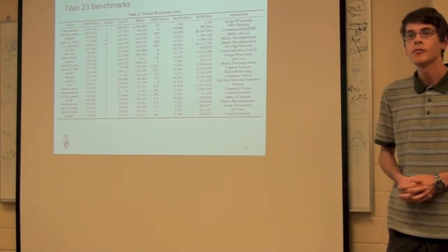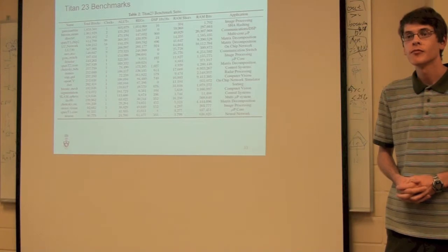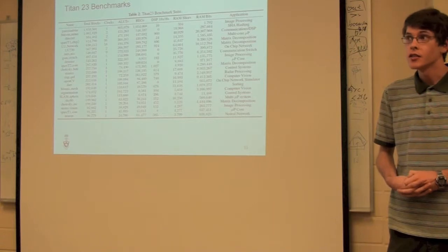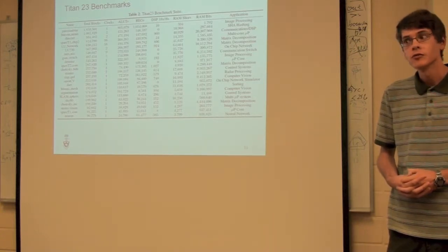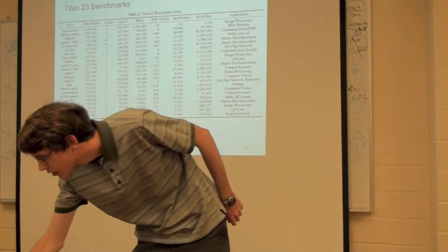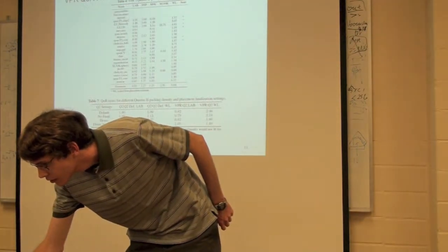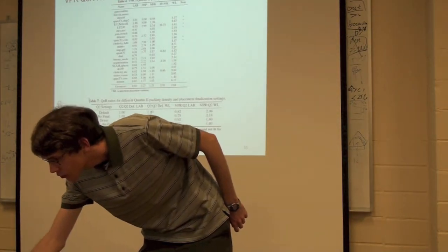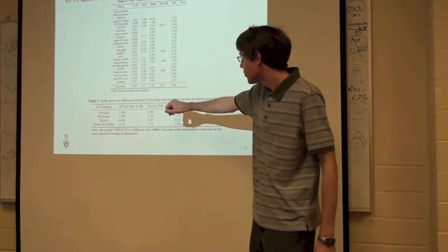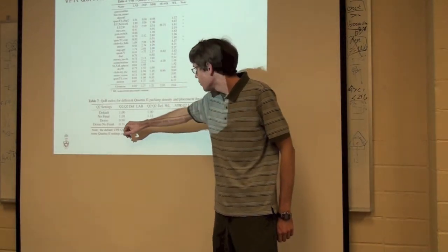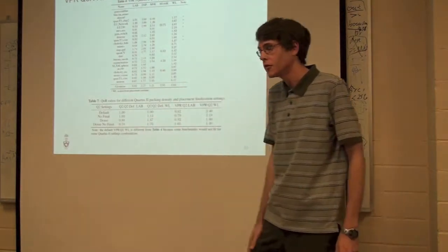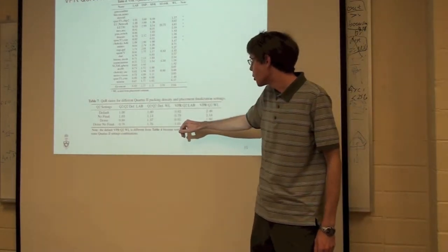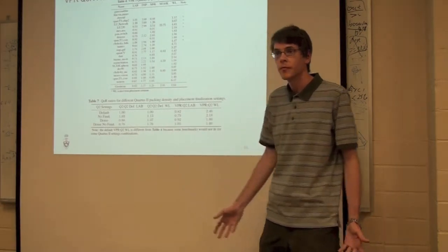Yep. About that argument, didn't you also mention that Quartus also beat you on the packing density? No, I didn't say that. I don't think I actually looked at it. Actually, I might have that. You do have logic elements. You said it was 30% less. But if you turn up the packing density in Quartus, you can get it down to about 78% of the original. We can't change VPR, but basically Quartus in its dense mode is fairly comparable to VPR.